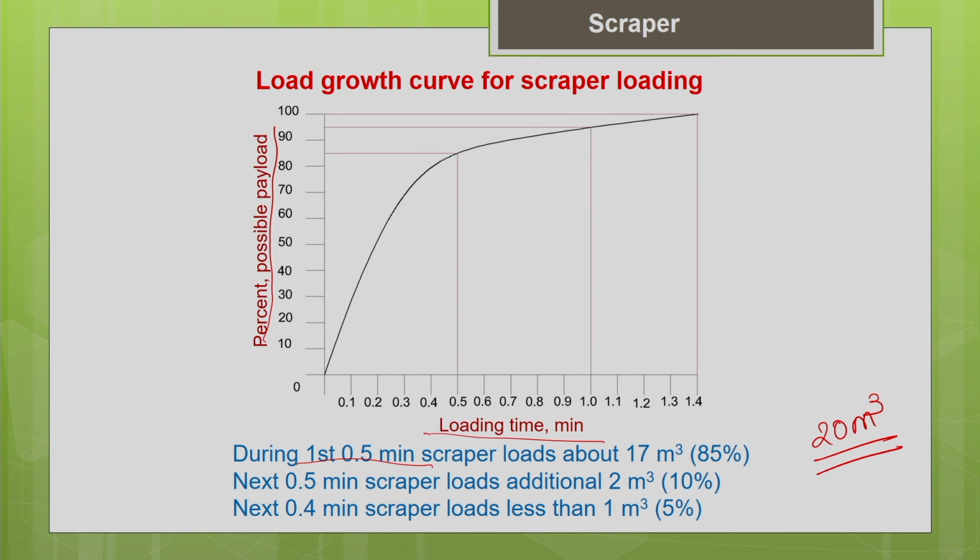Now, you are loading the material into the bowl. For the first 0.5 minute, your payload percentage is 85%. In the first 0.5 minute, I have filled 85% of the scraper bowl.